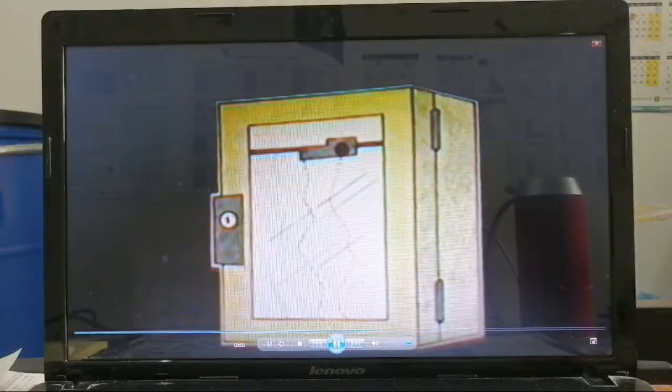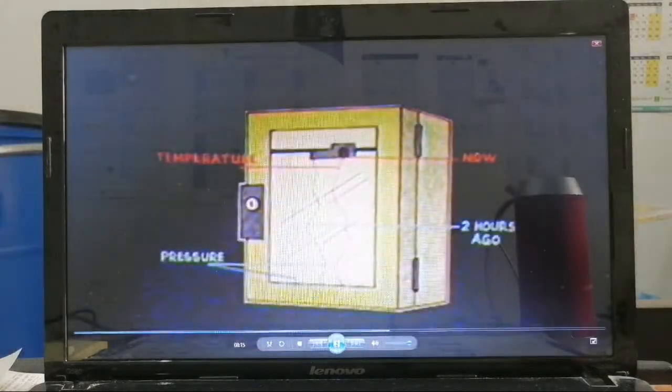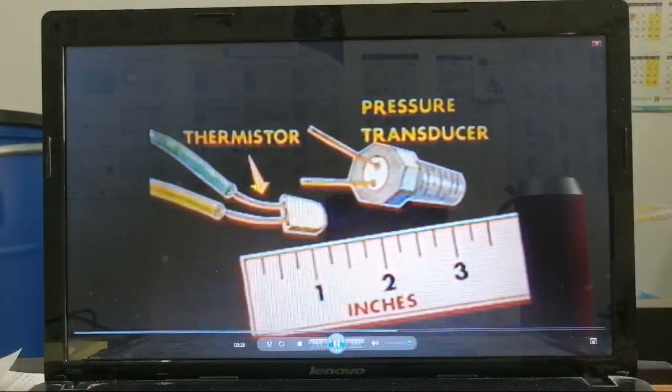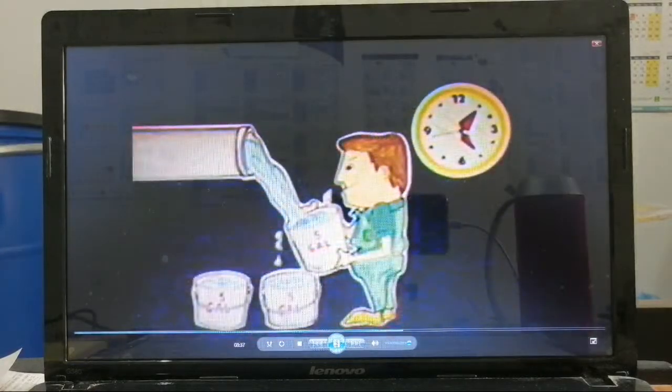Some recorders use a continuous roll of chart paper slowly moving past the marker. Many units can record 2, 3, or more signals on one chart. Now the operator can quickly compare several temperature and pressure readings to see how the system is trending. It is very helpful to know not only the readings now, but also what has been happening. Many semi-mechanical transmitting devices to measure temperature or pressure are being replaced by small solid-state electronic devices coupled with transistorized amplifiers. And what about flow measurement?